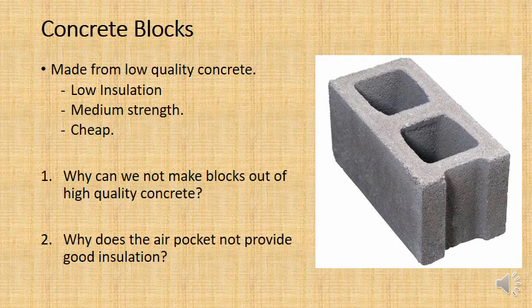It also gives it very medium strength. I think the standard is they need to be 20 megapascals in strength, but I've seen research to say that in Kurdistan they can be as low as 5 megapascals in compressive strength, which is quite concerning, actually. But the good advantage of building it out of a low quality concrete is it's very cheap.